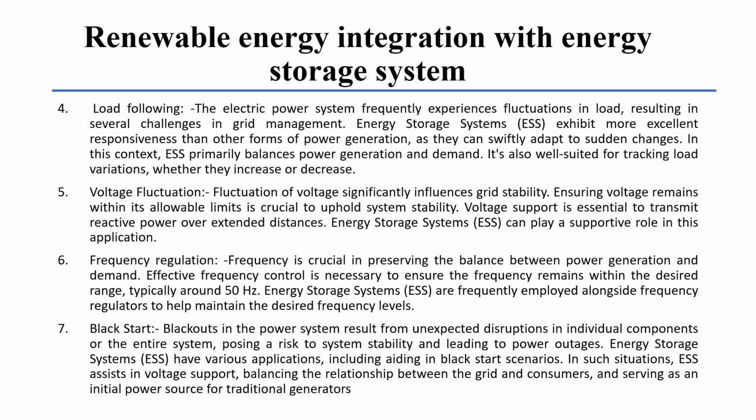The last one is black start. Blackouts in the power system result from unexpected disruption in individual components or the entire system, posing a risk to system stability and leading to a power outage. Energy storage systems have various applications, including aiding in the black start scenario. In such a situation, ESS assists in voltage support, balancing the relationship between the grid and consumer, and serving as an initial power source for the traditional generator.